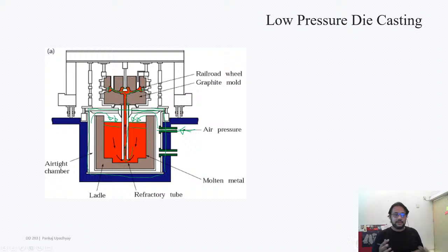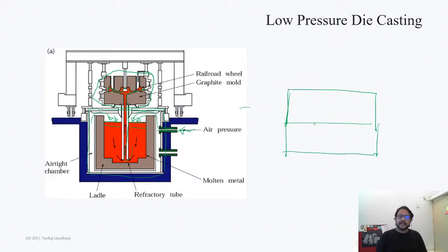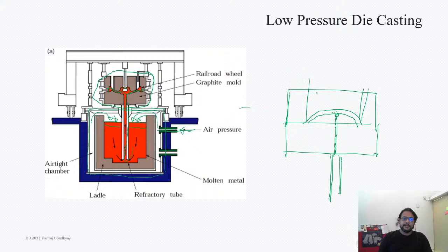In the casting cavity, this gray-brown thing is the die. So you have a die like this with both the cope and the drag pattern. In the case of die casting, it's called a top and a bottom. Here you have, let's say, the cavity, and this is the ingate, the place where the material will flow in, connected to that tube. Imagine that if I have enough places where the material can rise up, there are vents and risers, whatever material comes in flows into all of these locations and rises up to the top.